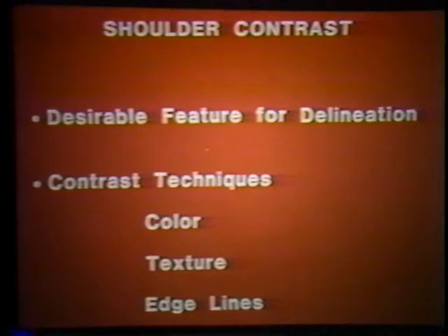Whether or not drivers actually drive on the shoulder, a definite contrast between the travel lane and shoulder should be maintained. The contrast can be achieved by color and/or texture differences between the two surfaces. This contrast shows drivers that the shoulder is definitely reserved for special purposes. Also, contrast of the shoulder helps delineate the travel lane in poor conditions such as rain or fog. Another important reason for contrasting the shoulder is that for areas where driving on the shoulder is prohibited, drivers can easily recognize the shoulder by color or the changed sound caused by the different texture.